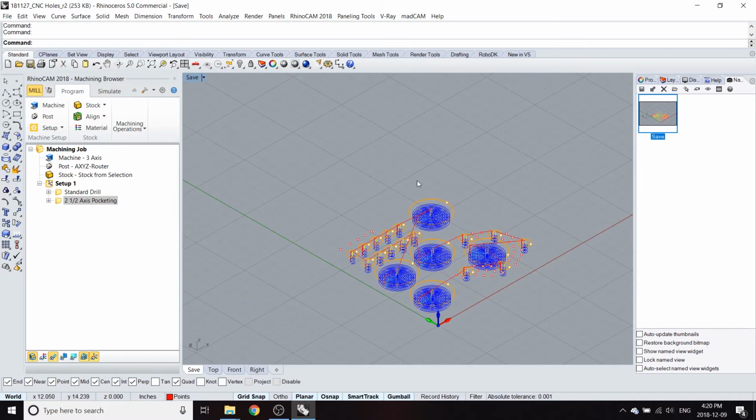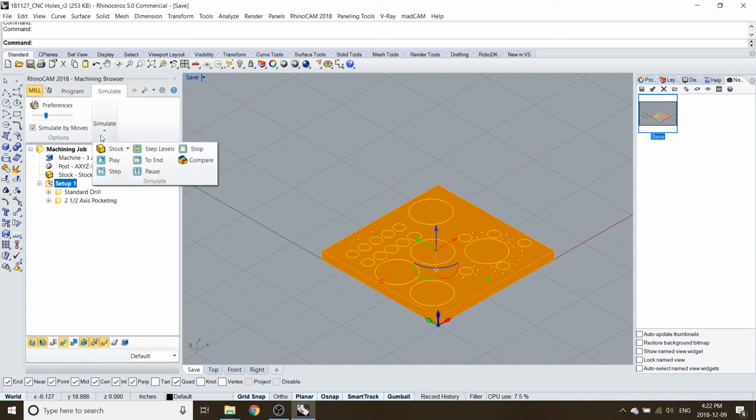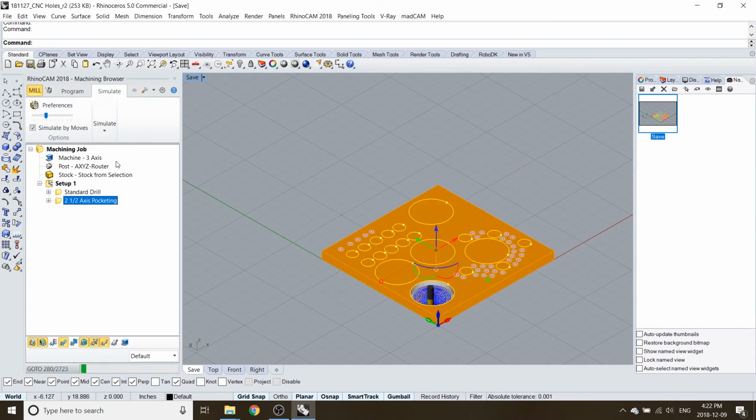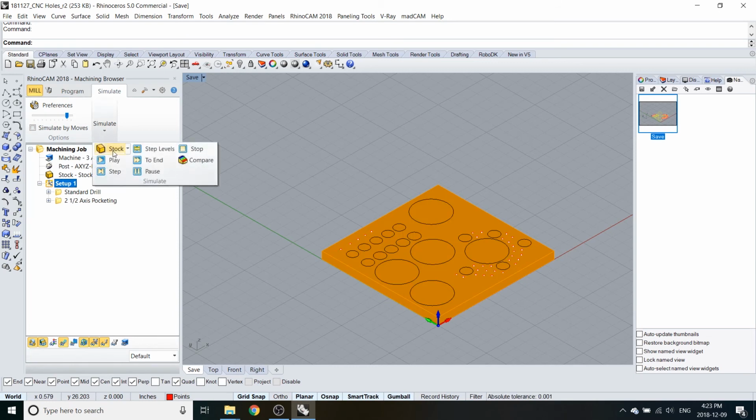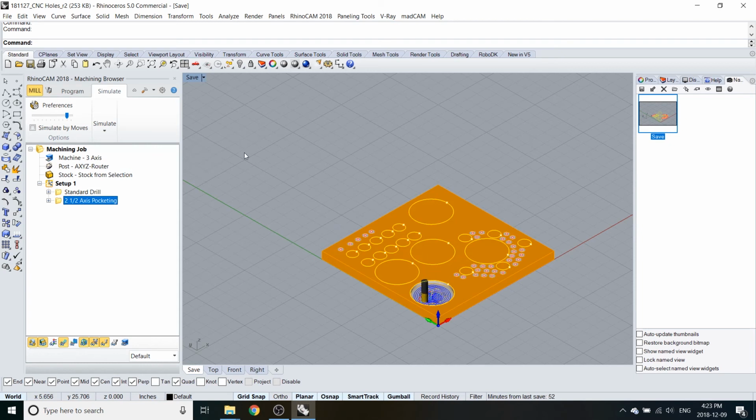To simulate a toolpath operation, go to the Simulate panel in the toolbar. Click the specific milling operation folder that is to be viewed and click the Simulation drop-down panel. Options are provided for controlling the viewing simulation in addition to speeding through the operations, which can be controlled using the slider on the left. Once commenced, the simulation will display the operation of the milling path with the specified tool bit. This will display the entire toolpath operation from beginning to end. If there is a collision with the stock material against the spindle, the cut material will appear in a different color.